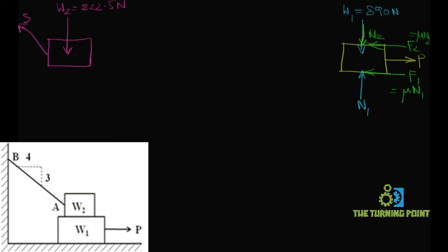And we have calculated theta, right? So that is with the horizontal. So let us keep it as theta here. And if you observe, this block is not able to move in downward direction. As it is not able to move in downward direction, so we will represent a reaction in the opposite direction perpendicular to surface. So a reaction opposite to it will become N2. According to Newton's third law, these two forces should be equal. Why?